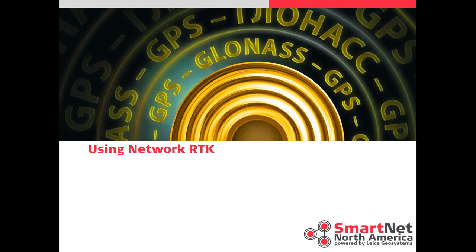So we've got some questions here. Does atmospheric error affect relative precision within the network? Yes, it can, depending on the time that you take the measurements. If you take one at one time of day and you take another one at another time of day, your relative measurements between your stations can be affected. When is L1 going away? Never, to my knowledge.